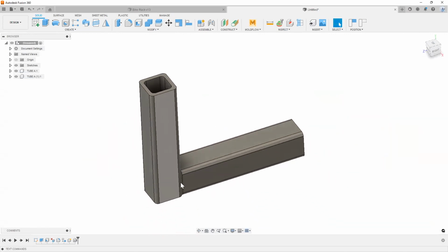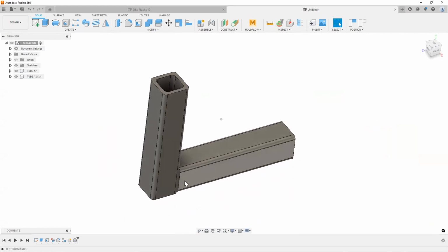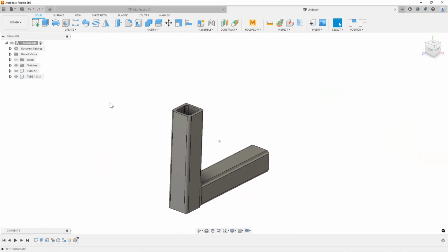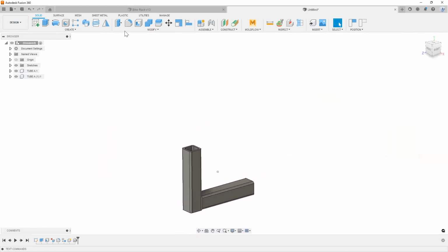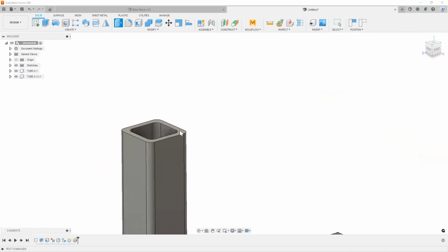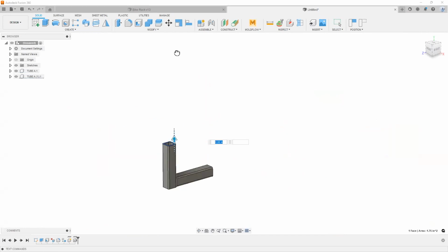If it wasn't, you would repeat the same process on the align for probably just one side of the face here. All right. So here's where things get really cool now, because I told you earlier, the press pull feature is kind of like a Swiss Army knife of a tool. Now, just by clicking on one of the faces, I can offset this to whatever height I need. All right.